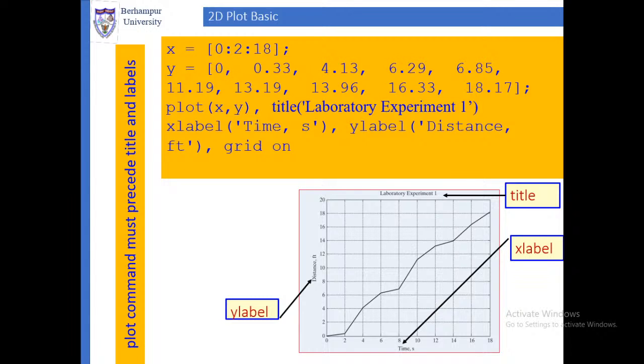If we plot that, the plot will look something like what is given below. We will see that in the next slide. So how to plot that? Give the command plot, all in small letters, within circular brackets x comma y. So x comes first, that will be the x-axis or the horizontal axis.